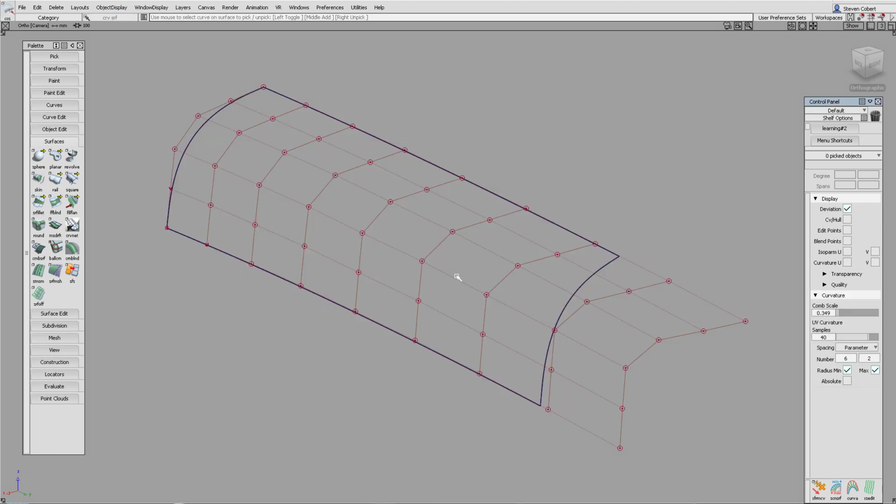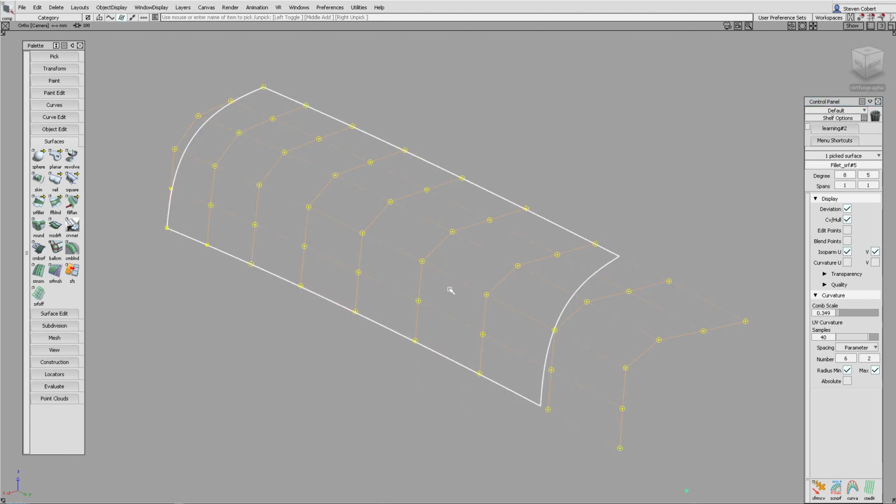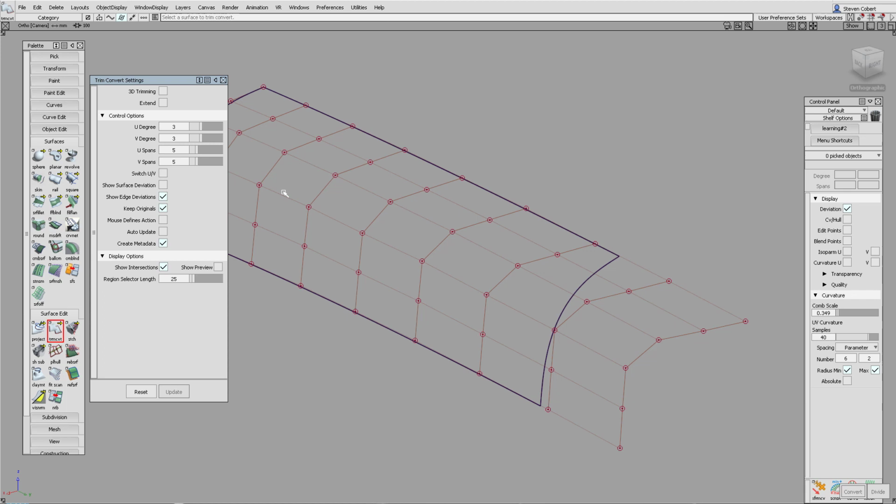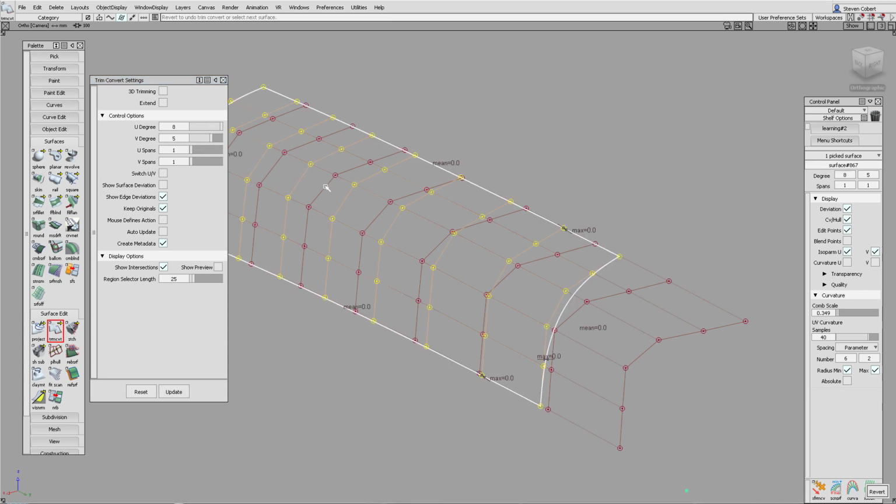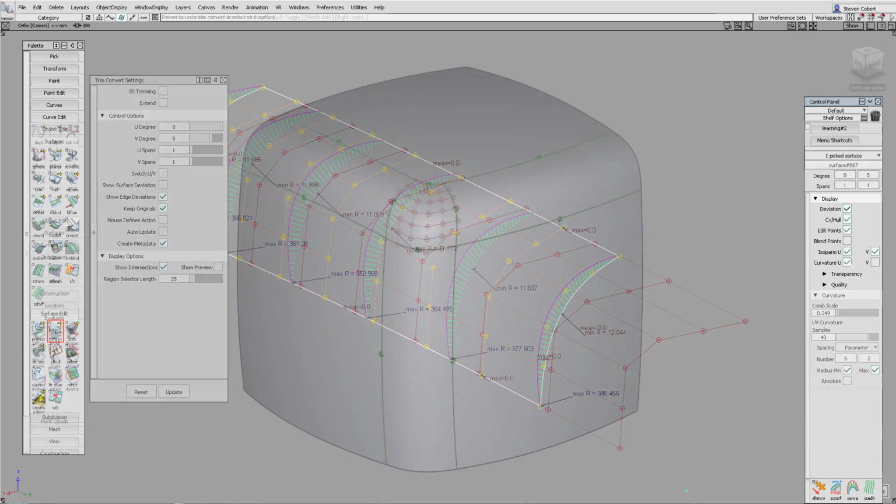Secondly, if we want to analyze the curvature across the fillet, then it's better to do this on the trimmed surface if the curvature sections are now true, i.e. they're at 90 degrees across the fillet, and therefore they give the correct minimum radius values. With an obliquely trim converted surface, the radius values are not the ones that we're after. For cast work, it's just easier to use the trim converted fillets only.